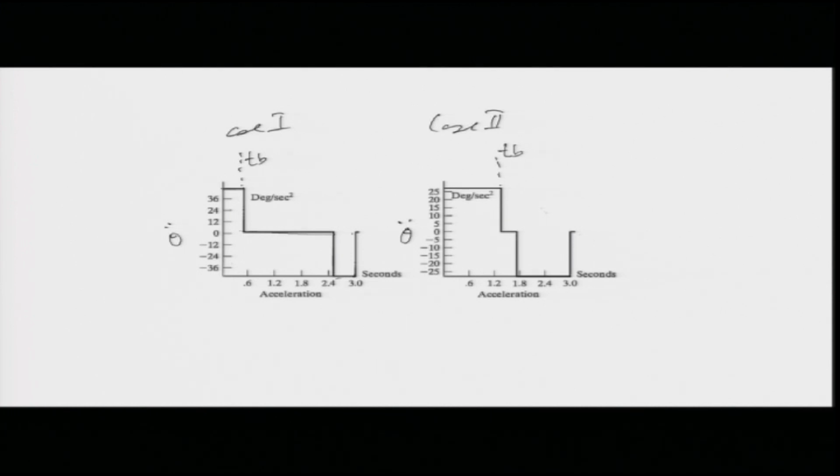In both the cases, this shows the effect of theta double dot on theta, theta dot and theta double dot. Today's discussion was essentially about how to find a trajectory. We have seen that for simulations we still use cubic splines. The problem of cubic splines in a real system is that a real system cannot accelerate in 0 time. So, we start the acceleration slowly and give it a parabolic blend there.